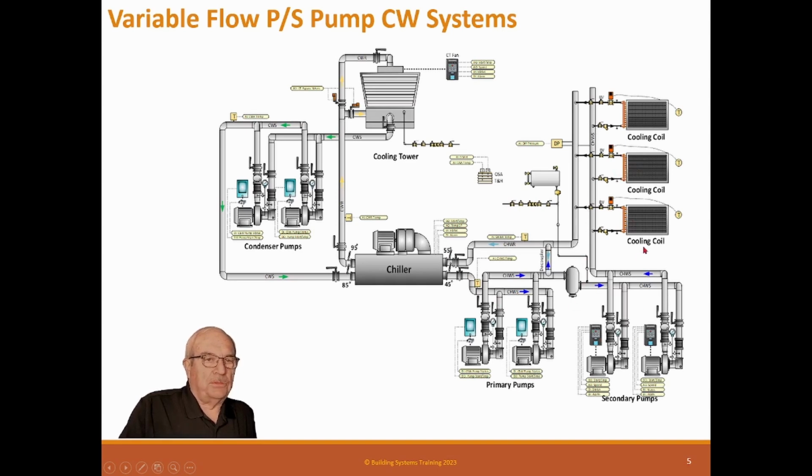Now let's go the opposite. It is possible too, if this is a very low load, or no load, which you'll never see, but very, very low load, then these pumps can pump this way through the decoupler and can keep this flow going. So these are two different flow loops that are completely independent of each other.